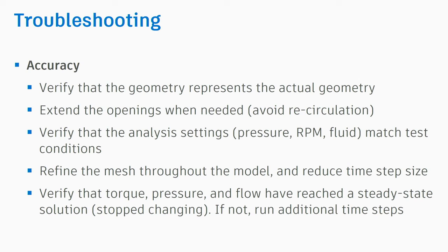They should help you. So please verify that the geometry represents the actual geometry. Some users go further with the cleanup of the model. They simplify, simplify, simplify till they change the model totally. This should be really avoided. Then make sure to extend the openings when needed to avoid having the recirculation at the outlet, which leads to a mass balance problem.